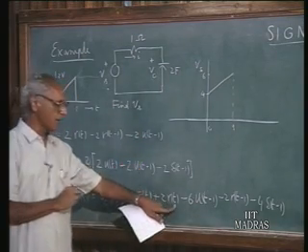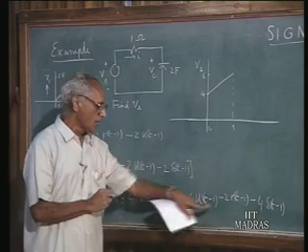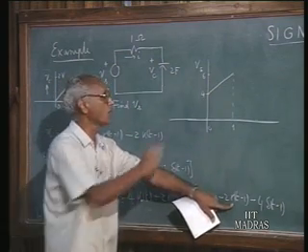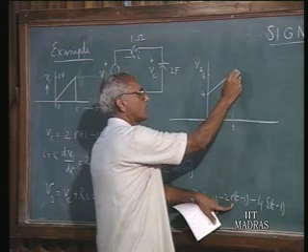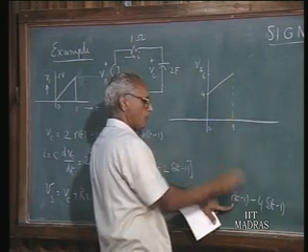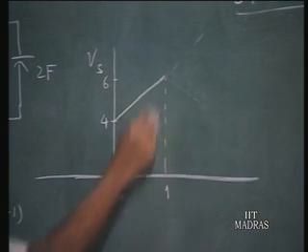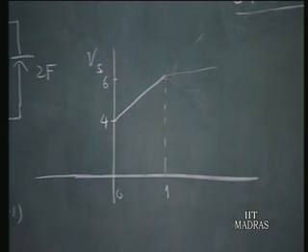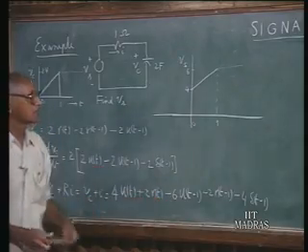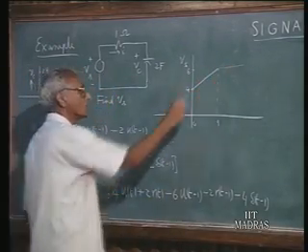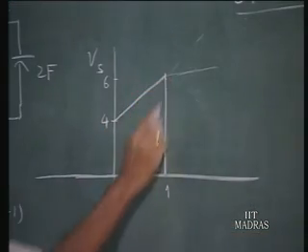At this point of time you have a negative going ramp of 2 units. Therefore, it means that whatever was increasing earlier is now pulled down by the same slope. That means if you added this function, it would have continued like this. But you also have a step of minus 6. So, instead of remaining constant here, this will come down here by 6 units.